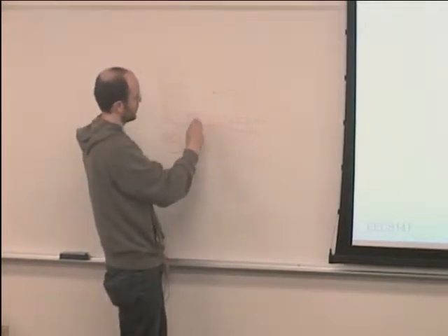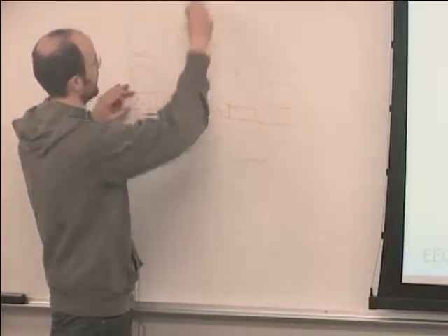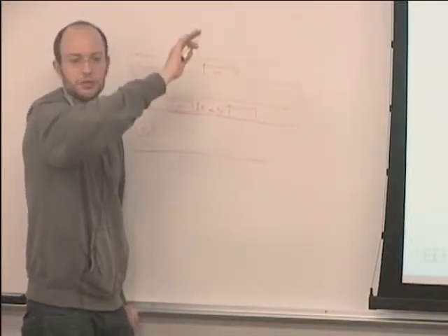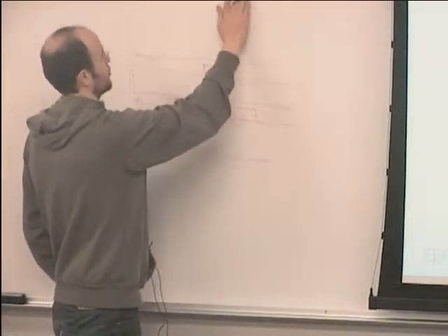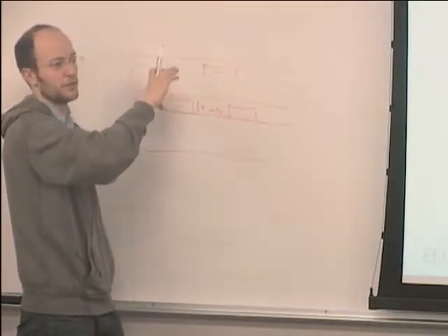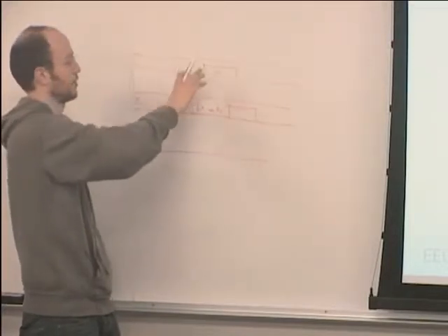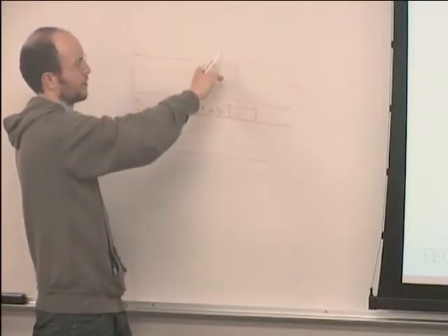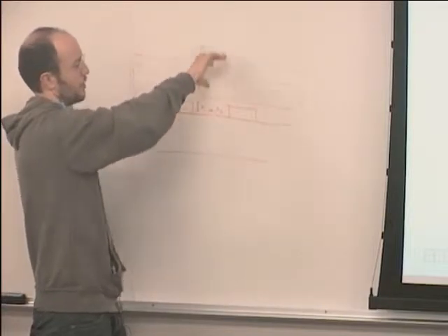Now, you can also imagine that if you have a wire down here on metal 1, and there is a wire up here on metal 9, okay? The capacitance between these two will not be very large. So to first order, it's probably safe to consider capacitors that are one layer away. But there could be cases, not so much in digital, but maybe in analog situations where you want to really calculate this capacitance very carefully, and then you can of course do it by hand, but most likely you will do it with some kind of extraction tool.